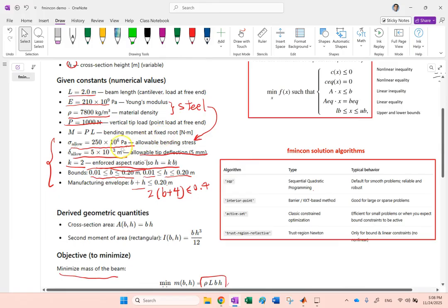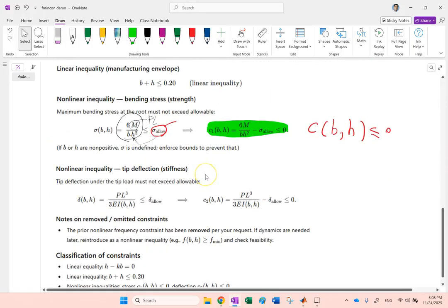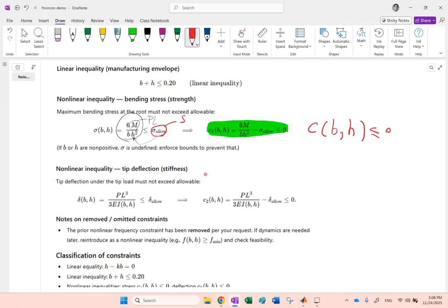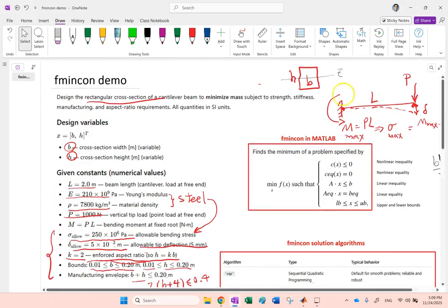Here you can see that that number is just given to us. If we had the yield strength of the material, typically this is the yield strength divided by a safety factor. And by the way, here I'm neglecting the effect of the mass of the beam itself on the stress and the shear force at the beam. So I'm using a very, very simple formula for sigma max.